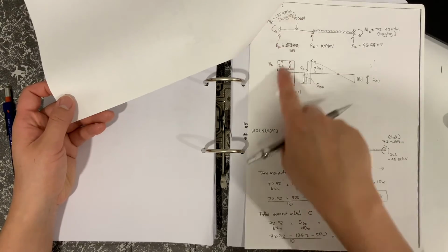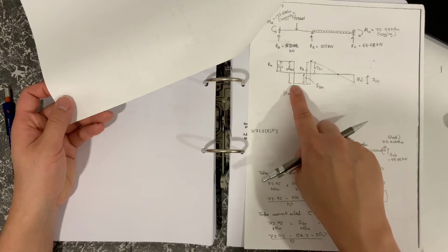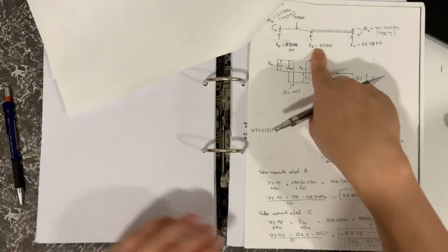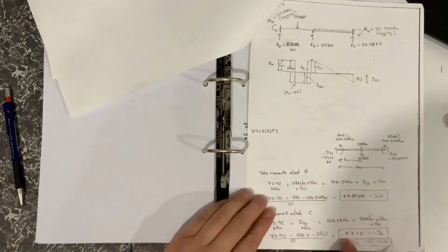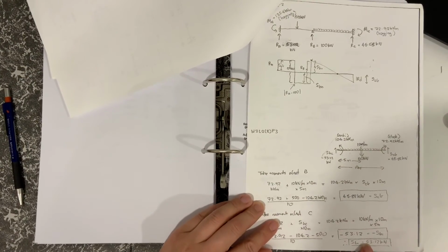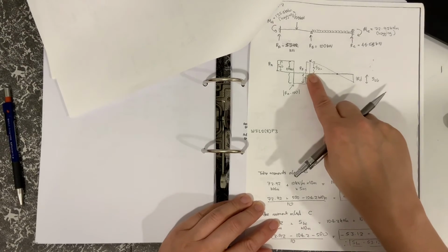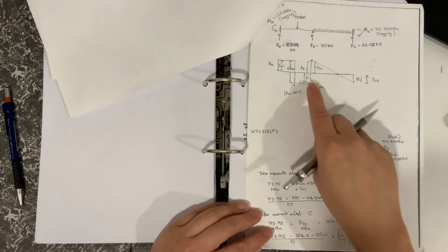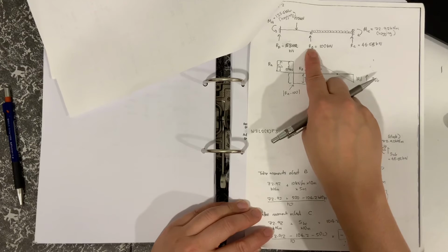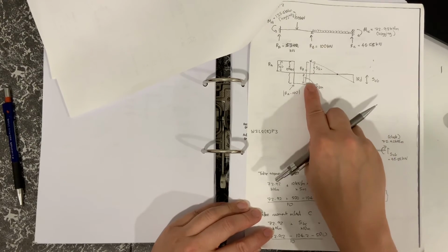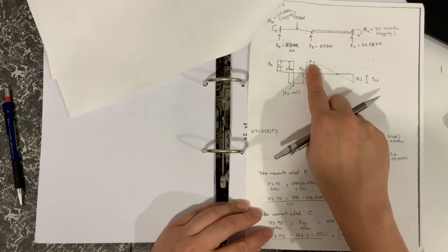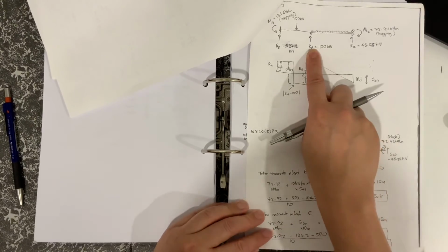Shear force up, which we can see there, down by 100, then goes up and goes back to 0. And then for the second span, which would be span BC, we would see the shear force is 53.12. So SBC would be from there to there, which is 53.12. And then the total reaction at B, which would be that value there, would be that value of the shear force to the left, plus that value of the shear force to the right,